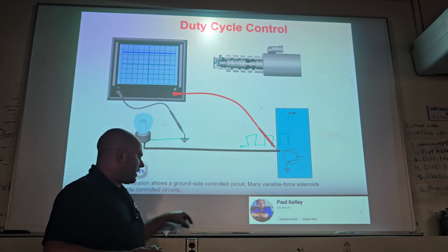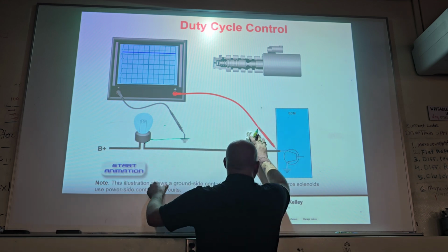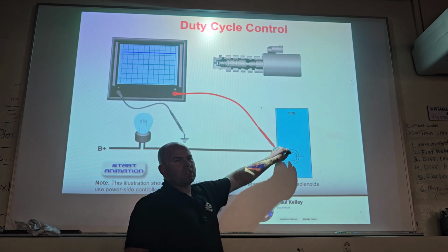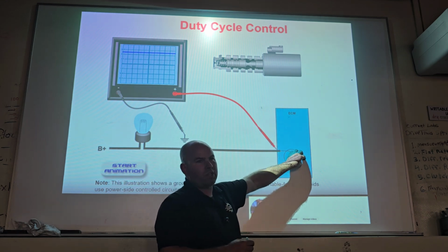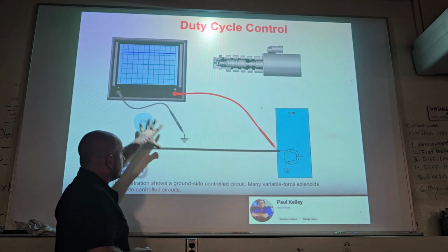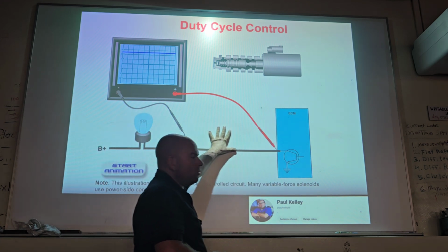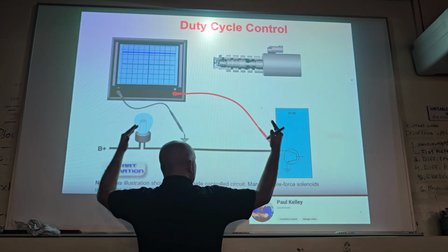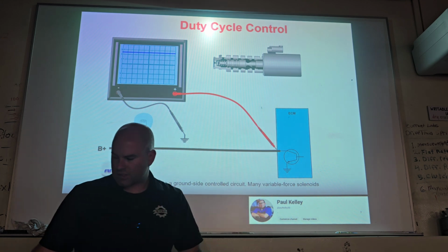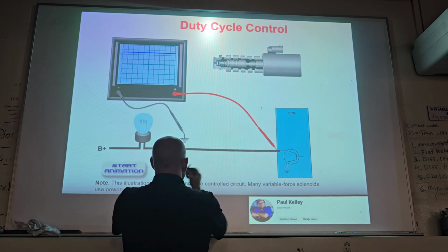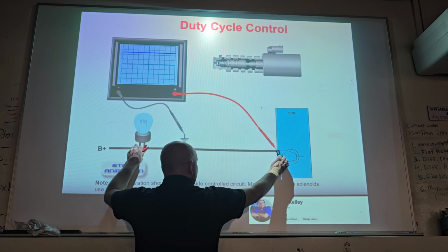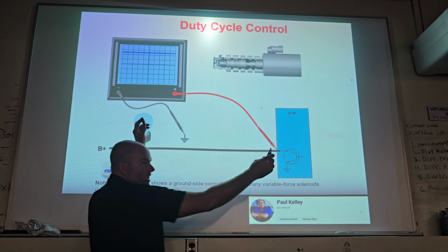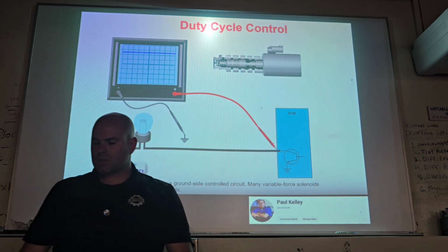So that's how, again, you can bust out the picoscope and the picoscope can give you really good info, but ultimately, you're not really trying to diagnose typically how exactly this transistor is working. You're more like, is it a wire? Is it a solenoid? So you could shoot right for duty cycle on this, but probably what I would do, if I thought it was this wire, couldn't I effectively figure it out like this with my meter? Just put it on resistance, do my 12 volts and do my ground, or do my resistance measurement right here, boom. And if it's an open wire, what do I get on resistance? Oh, well, yeah, exactly. So there's a lot of different ways to do the diagnosis.